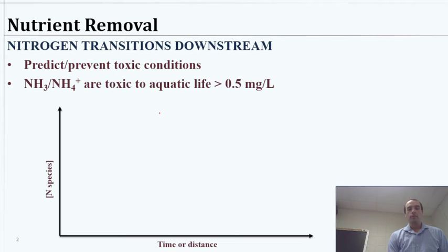And the thing is that when we add some form of ammonia, so let's say this is time 0 down here, and we add a sudden input of ammonia, or let's say we just add fish, and they're going to excrete ammonia, urea, things like that, especially if you feed them a lot. If you do ever start an aquarium, put something small in it that you don't care too much about, or even just put some source of ammonia and let it sit there for a couple weeks with aeration going.